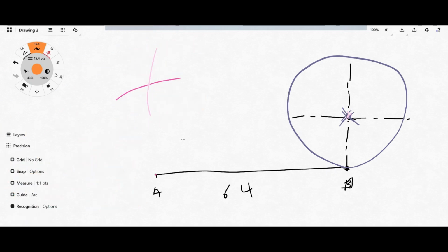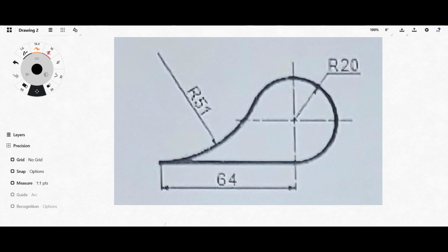This will be the center point for the second arc, right? So you come here, because we found this to be the center point for the arc, and you open up to a radius of 51 millimeters. It should touch here. So if you stand here and open up to here, it should give you 51 millimeters. That's a way to know that you've done your work well, right?